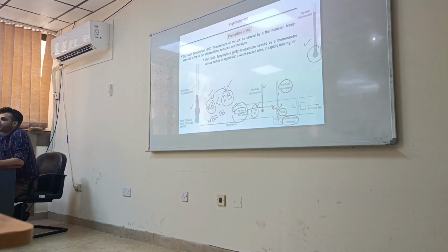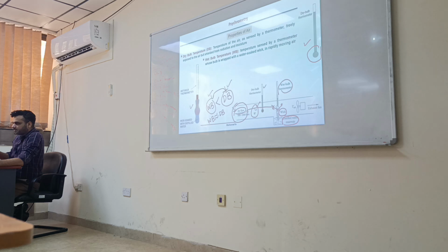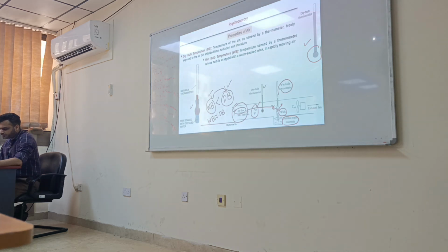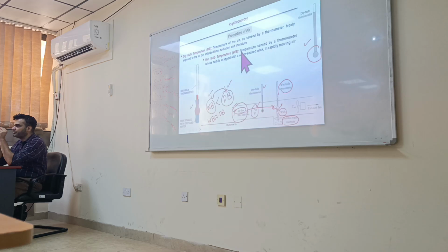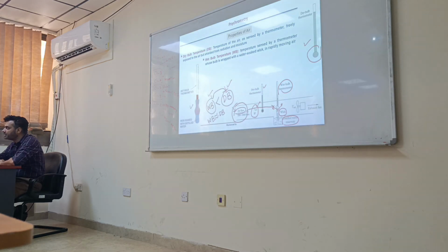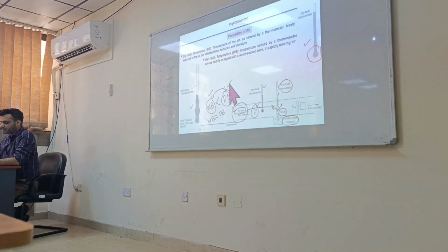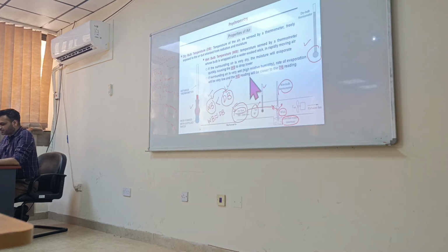So in all those weather data stations, what they are doing, they are measuring these two temperatures, dry bulb and wet bulb. Based on this, they find out how humid the air is. Right? The difference. Yeah, the difference, but how to convert it into humidity, we'll see now. Or those psychrometric charts which have been developed. So if you know dry bulb and wet bulb, you will have a point. Now you can read how humid that air is. Okay. So these two terms are clear.